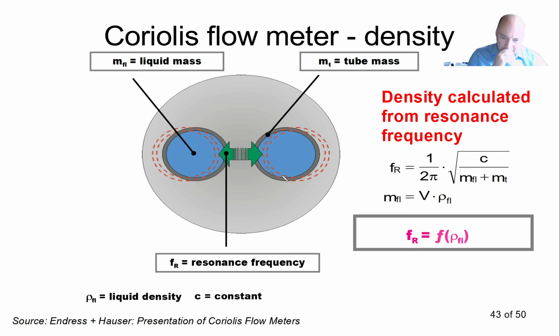And so here we can see how it works. We have the pipe, it's moving back and forth, left and right, like that, and we are measuring the position. The flow meter, based on the Coriolis principle, does not have to measure only the mass flow, but it can also directly measure density. Because if you imagine, for example, water and honey, you impose some vibration, then this vibration will definitely be different, because we have different densities.